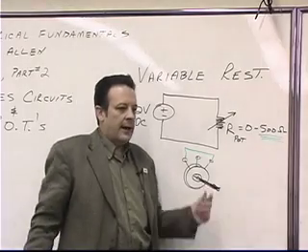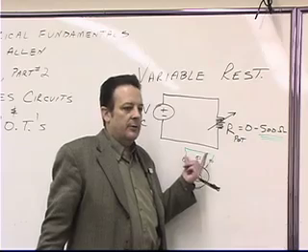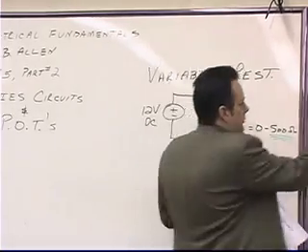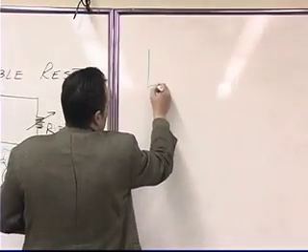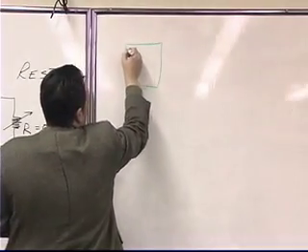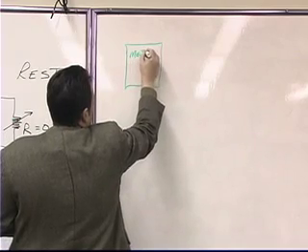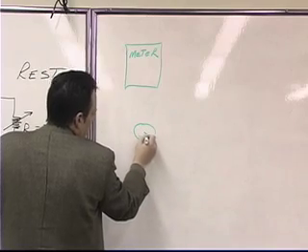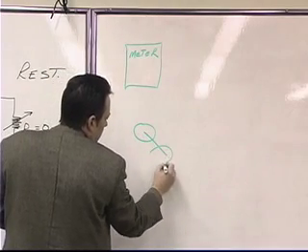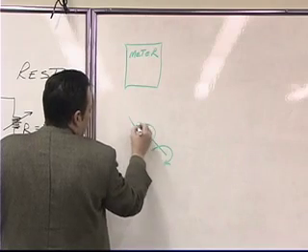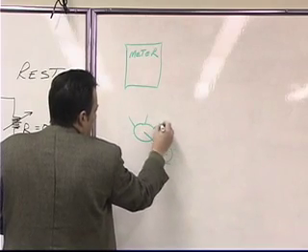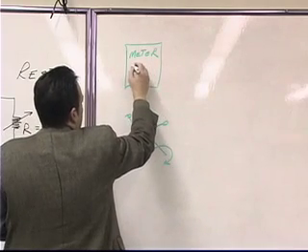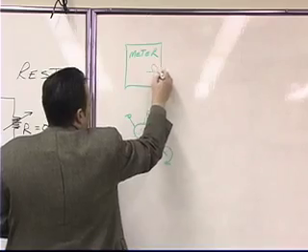But what I'm really getting at is what happens to the value on your meter if you connect your meter. In other words, if this is your meter, and this is your potentiometer, and you turn it clockwise, and you have 3 leads, and you set your meter to measure ohms.